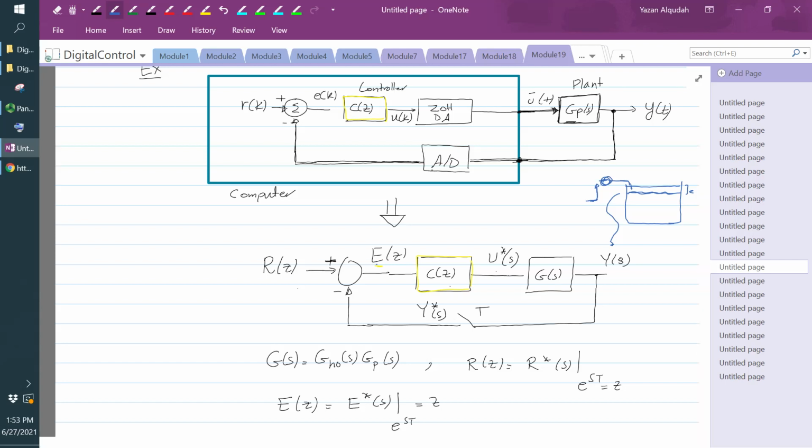So I have the error signal here, E of K. Now, if I know the error signal, I can just apply it directly to the motor that is going to be adding more fluid, or I can manipulate it and have it changed according to the filter that I'm adding here. And that is why I'm adding this filter. I'm going to take this error signal, apply a filter that takes E, the error signal, and generates U at the output, and that signal is going to be applied to the plant instead of applying the error signal.